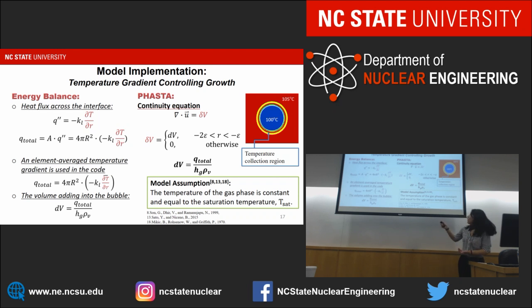And after we have this temperature gradient, we're able to calculate the heat flux across the interface, and then convert this heat flux into the volume increase term, and add this volume increase term into the continuity equations to support the bubble growth.